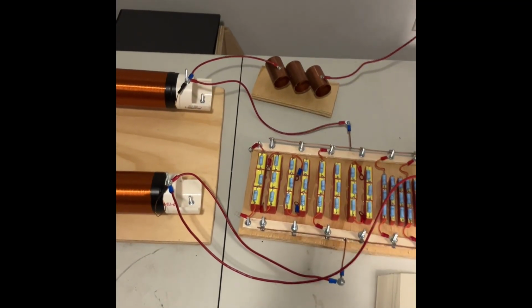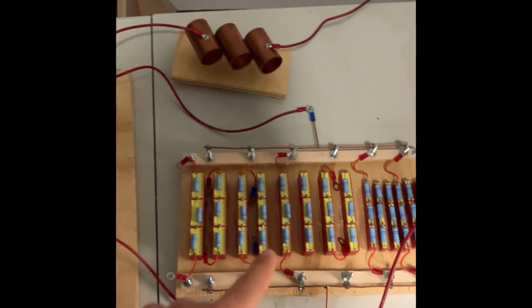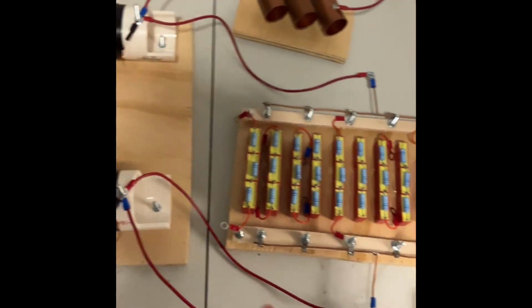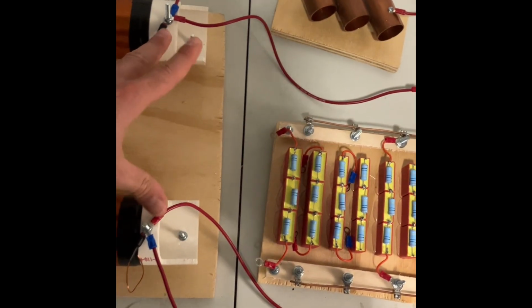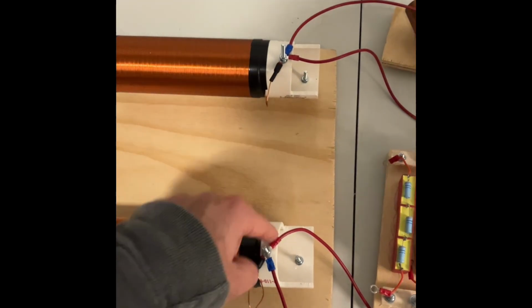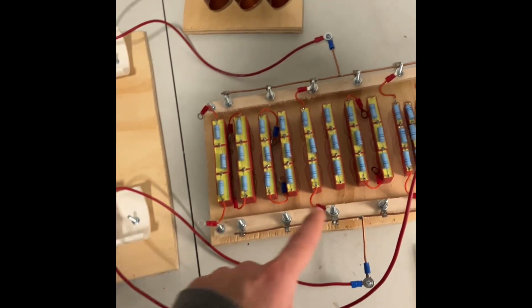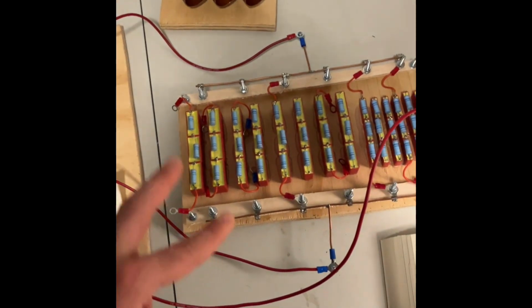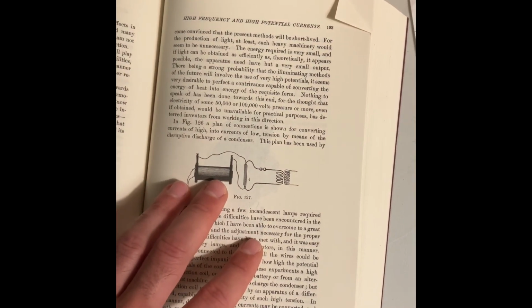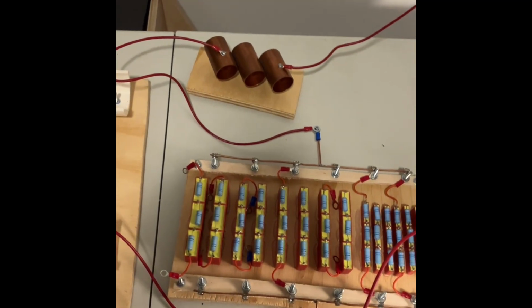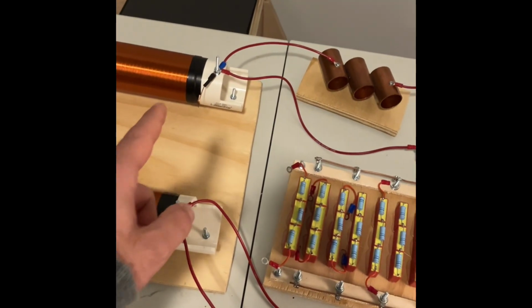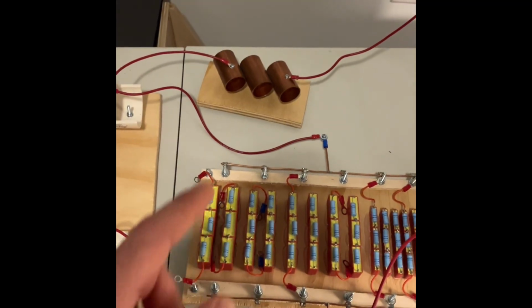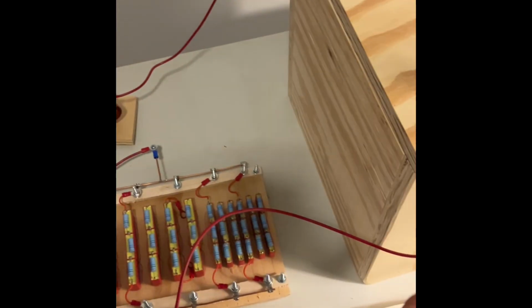You may have noticed that, since my last video, I did notice that I had the capacitor and the spark gap switched. Where I had the spark gap, I had the two outputs coming from the neon sign transformer going across the spark gap, and I had the capacitor in series with the transformer. So I've just swapped the two. It'll work either way, but like I said, we're just trying to keep as close to what is described in this book as possible. So I did just go ahead and swap the two. So now we have the output from the neon sign transformer going across our capacitor bank, and the spark gap is actually now in series with the primary of the transformer.